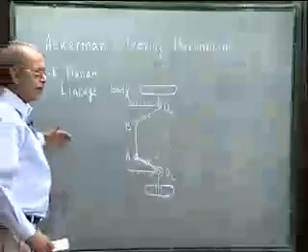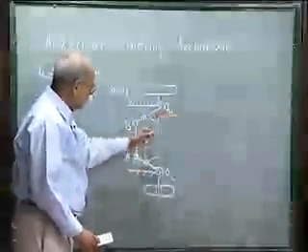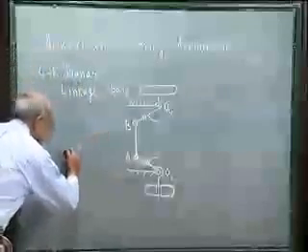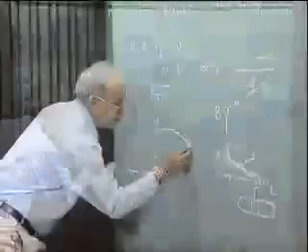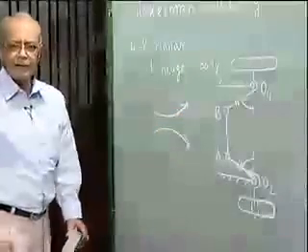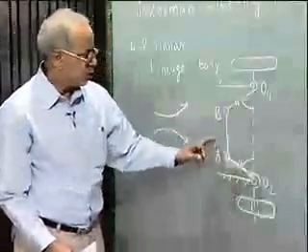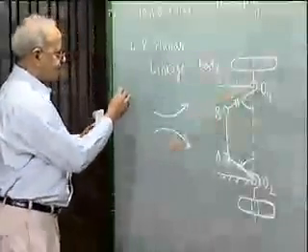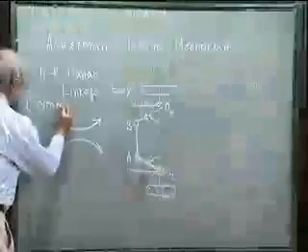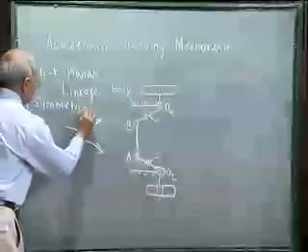While the car is going along a straight path, these two angles must be the same, because it has to be symmetric, as the car may take a right hand turn or a left hand turn, and these two turns must be identical. So this linkage O2 A B O4 is a symmetrical 4R linkage.